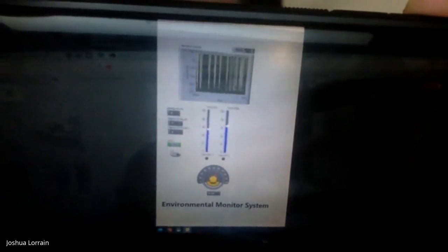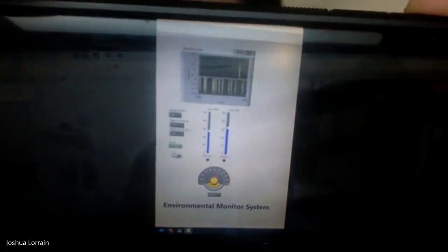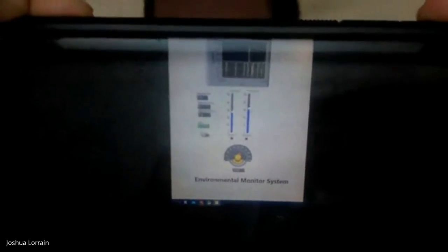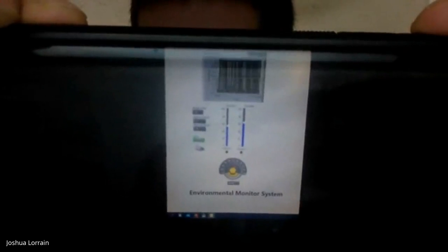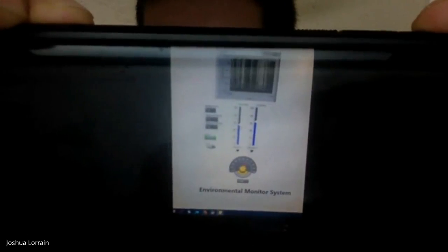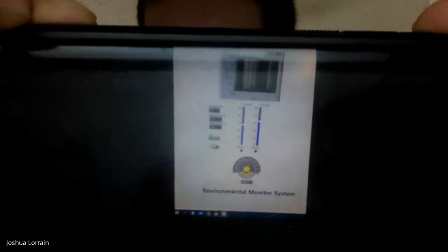We can reduce this by adding a voltage regulator or more filters, and that's the idea behind this first capacitor and resistor. You can continue to add more of those if you really want, but this does the job just fine. So let's get into it. When the temperature sensor goes above, I've got it set about 65 degrees, it will kick on one LED. And when it goes below 55 degrees, it will kick on another LED. So let's see it in action.